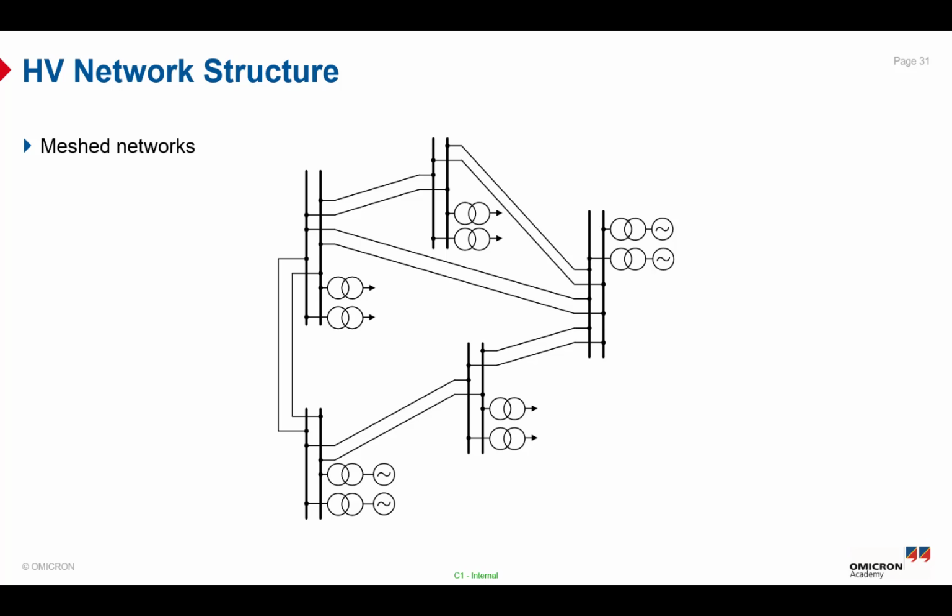So you can see from our mesh network here the incoming feeder with a step-up transformer and generator. Also, we have the outgoing feeder with a step-down transformer or coupling transformer, for example, from 380 kV to 110 kV. We have also the substation double busbar systems, and this arrow represents the connected load or the outgoing feeder.